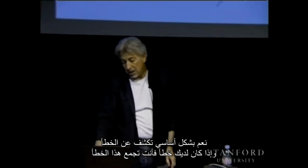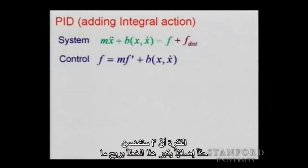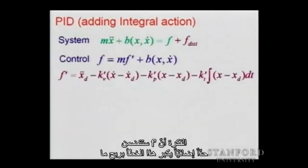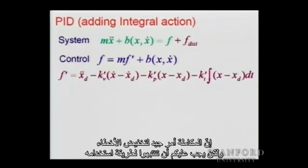So essentially, the idea is now your f prime will include an additional term that magnifies this error with some gain, and keep magnifying and keep adding until you overcome that disturbance. Now, integral action is very good to reduce errors, but you have to be careful about the way you use it.